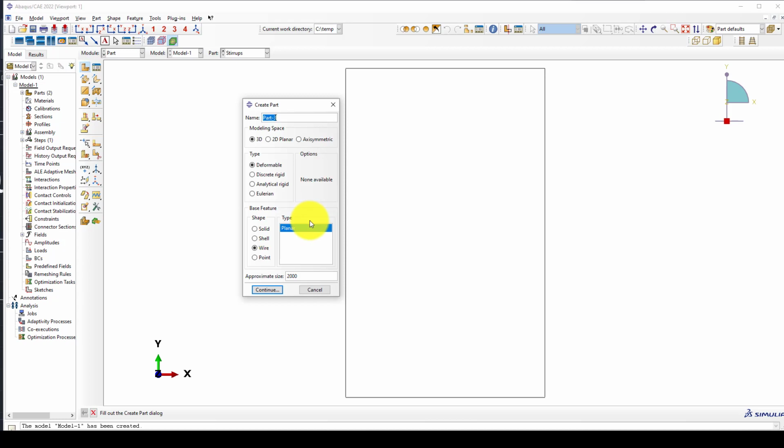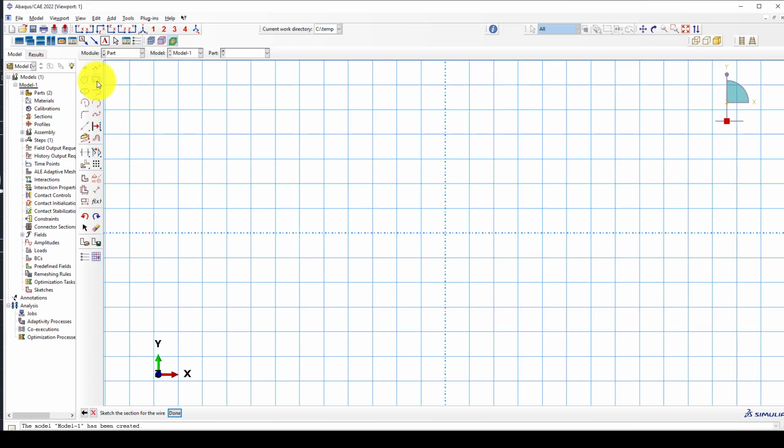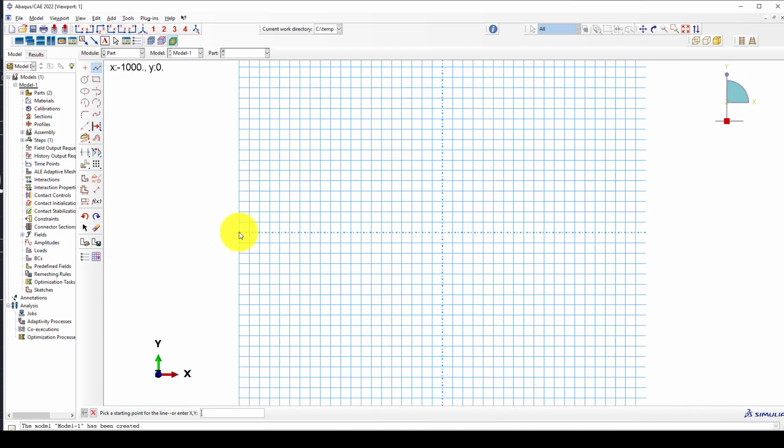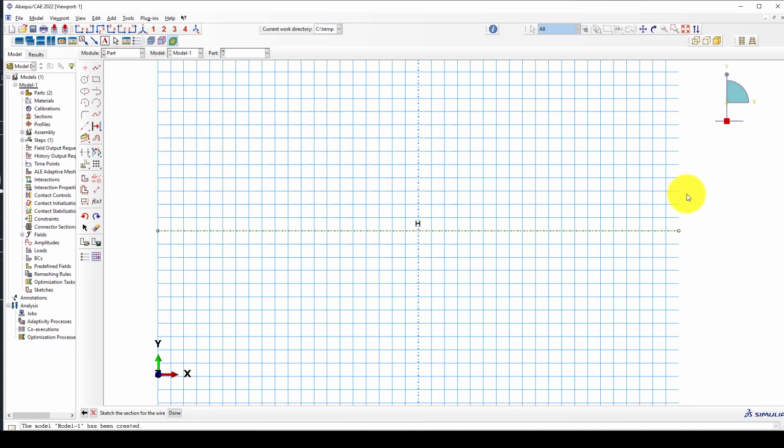we want to call rebars or longitudinal rebars. The longitudinal rebar is from this point to the 2 meter. We want to give a 20 millimeter cover on both sides, even though we can ignore that one, it's okay. Let's suppose it's the same as the length of the concrete.